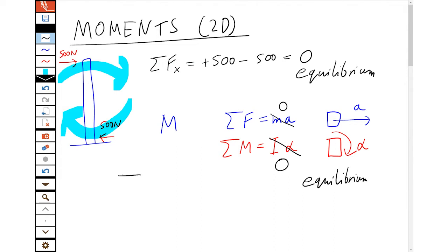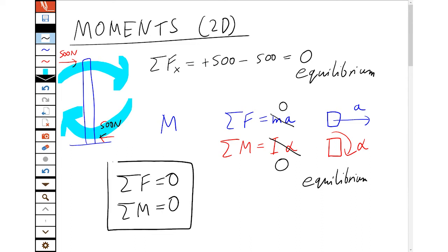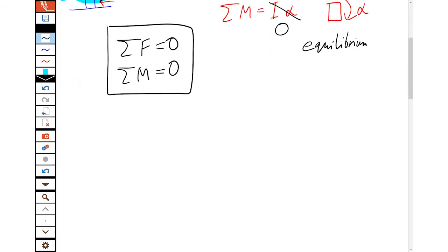And we're going to write those again because these two equations are the core of almost all the questions of everything here. The sum of the forces is 0 and the sum of the moments is 0. Everything adds up to 0. Pretty depressing sounding lesson for first year engineering, but extremely accurate and very useful. So if we know the moments must add up to 0, we better know how to calculate them. There's a few different ways we can get a moment.